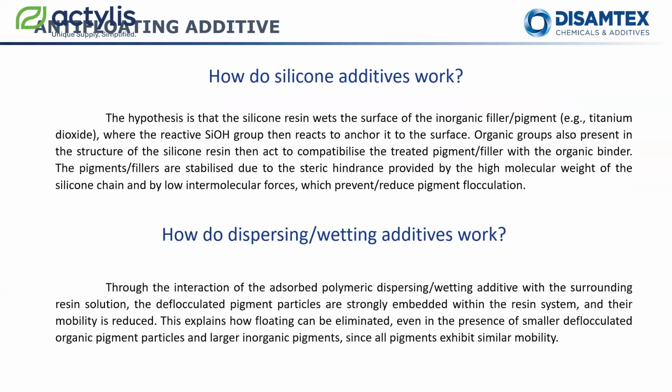Additives with silicone, like AF 504S, work by anchoring onto pigments, improving wetting and surface compatibility, and their structure stabilizes pigments through steric hindrance, reducing flocculation.